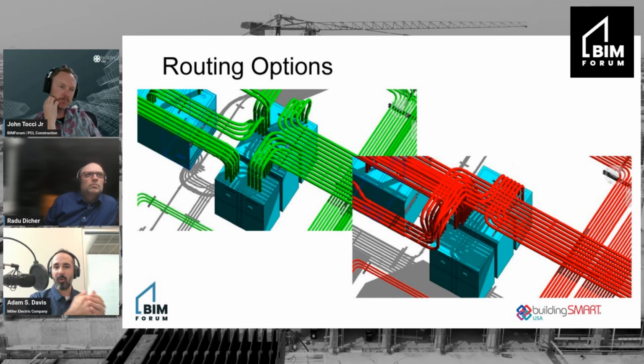It will look at wall-based hangers versus overhead-based hangers. It'll look at the supports. It'll look at what you've specified. So again, you can upload your custom spec. So if a certain client is saying every time you're a foot away from a bend of a piece of conduit, you need to support that, you can build that into the training of the tool.